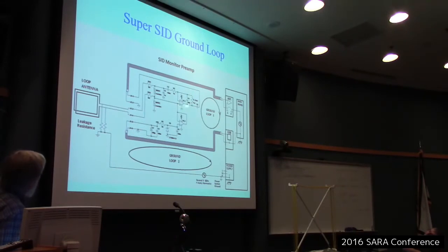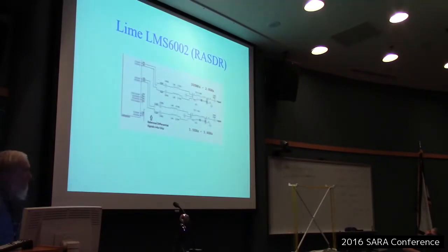An instrumentation amplifier would be good to use here, except that instrumentation amps are quite a bit more expensive than a vanilla op amp. Because the SID is quite cost sensitive, that may not be a practical solution. There's another architecture called a current amplifier, I believe, that might work too. Current mode feedback, I don't think, would solve that one. You still tend to show up with the same ground loops. Current mode feedback is a good way to extend bandwidth for a given silicon technology. That's its main claim to fame.